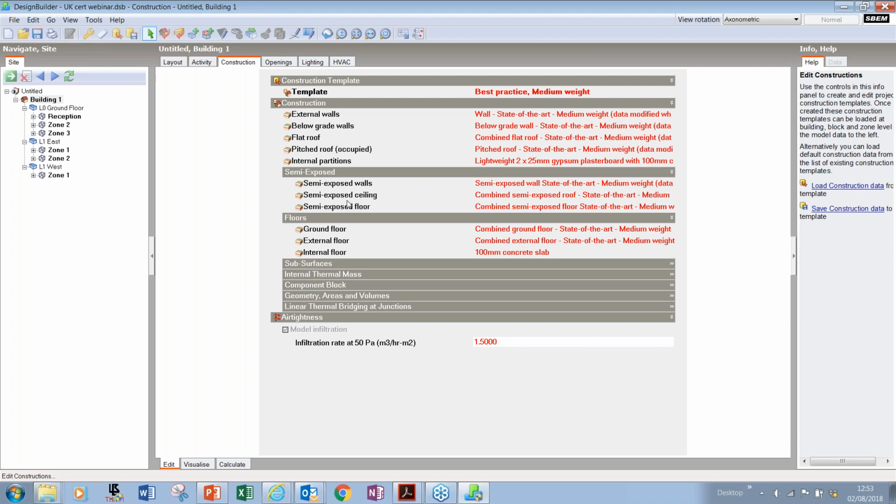There was previously in model options an option to model semi-exterior unconditioned zones as simple R values. Well, that option's now been removed, and all semi-exterior zones are now modelled simply by setting the zone type in the activity tab as semi-exterior unconditioned, or when you create the roof block or something, then you set that at that point in your SBEM or DSM model.